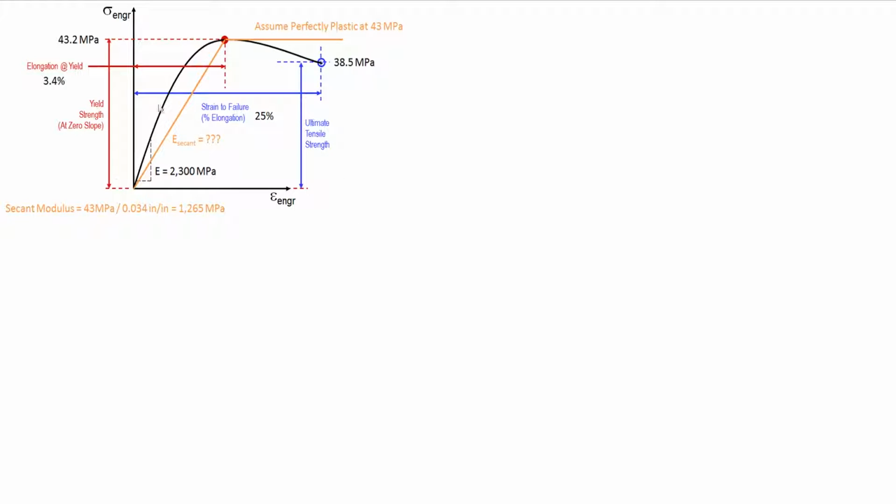So stress is measured in pressure, which is PSI for English or pascals for metric. If you're not familiar, those are the units for pressure, and the equation for pressure is force over area, but not necessarily an external force. It's internal force over area. That's basically the internal force inside of the material, because what we're talking about is the internal stress inside of the material. So internal force over area, that is stress, which again is measured in PSI or pascals.